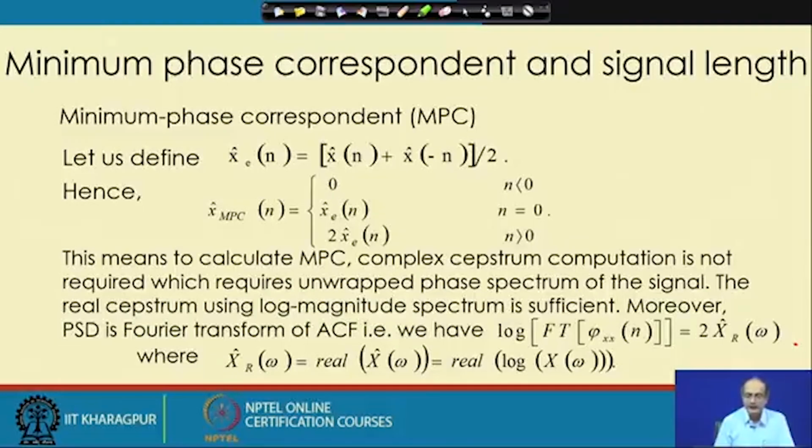Moreover, for the PSD, the Fourier transform of the ACF, if we take the log of it, we get twice the real component of it, and that way we can make use of this fact to find the even spectra.